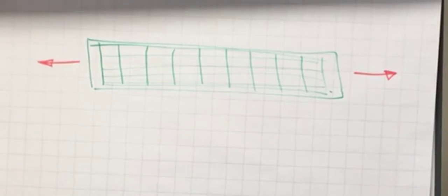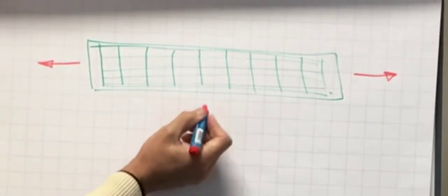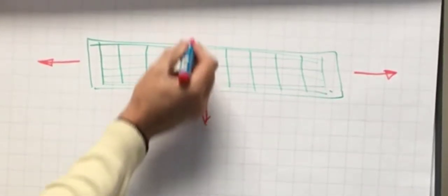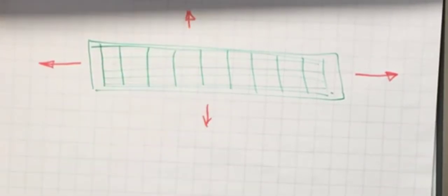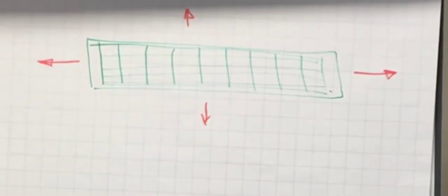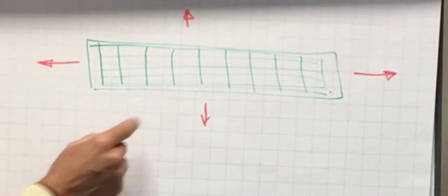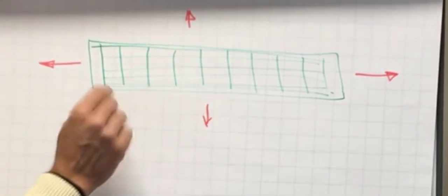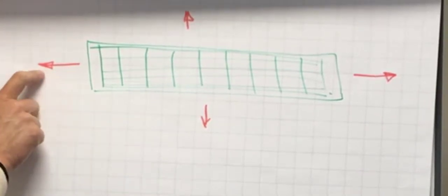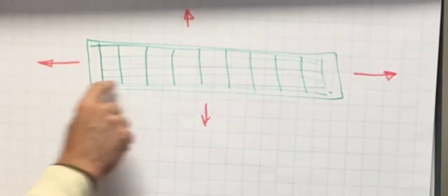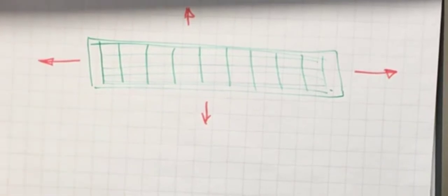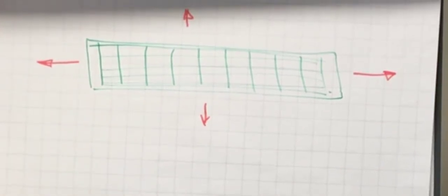But because we have fibers in the other direction, it means that we can also load the pipe in two directions. And this is basically where the microcracking problem starts. Because these fibers, the vertical fibers, they don't work in the horizontal load and the other way around. The horizontal fibers, they don't work in the vertical load.